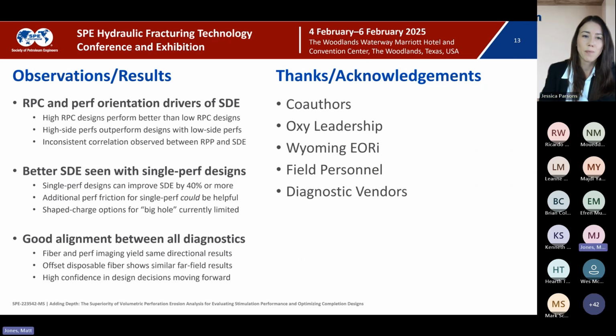So that's a really good question. I would say that for other projects I've worked on, that is actually not common. But the reasoning behind that is more than just, is it composite or is it dissolvable? The dissolvable plug that we used in this project is very similar in form and structure to a traditional composite plug, meaning it's not small, it's quite long. It's also got an OD, or an outer diameter, that's close to casing drift. It also has a very long sealing element relative to other dissolvable plugs. It also happens to have top and bottom hold down buttons.